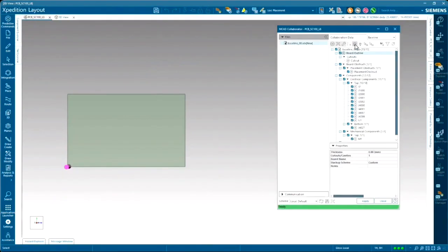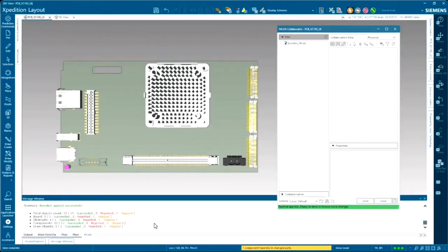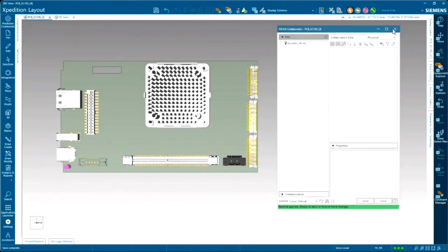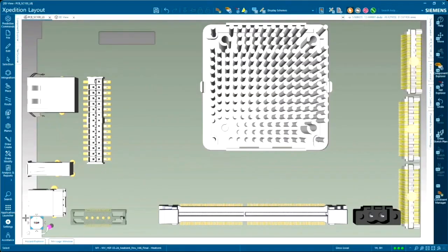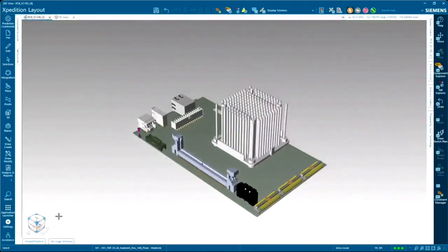So here we can see in the preview, I can preview the board profile with this ghosted image. I can inspect individual components and look at their structure and their definition. For each one of the components, the board, the mounting holes, and so on. And this gives us a good insight into the overall design. And when it's applied, we can now see exactly what we had on the MCAD side in the ECAD side. And the baseline communication is complete.